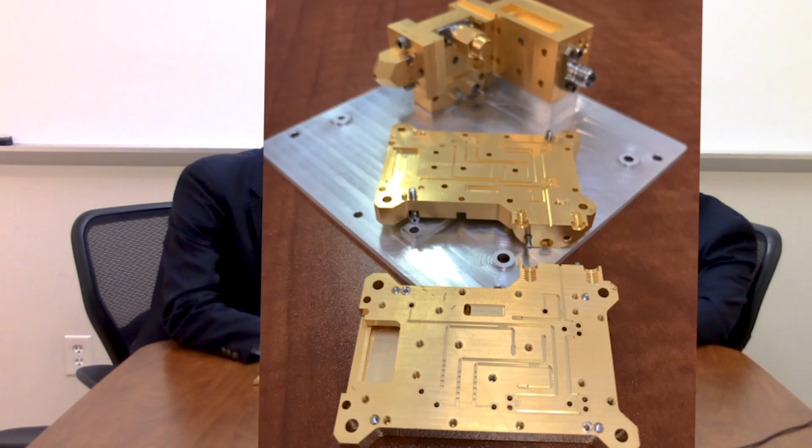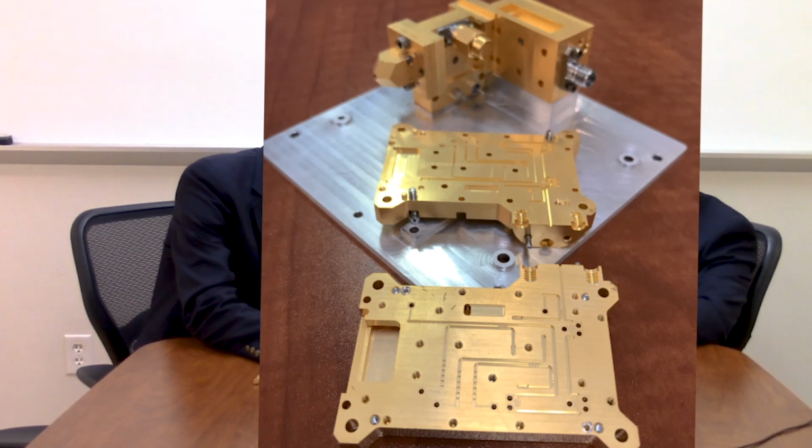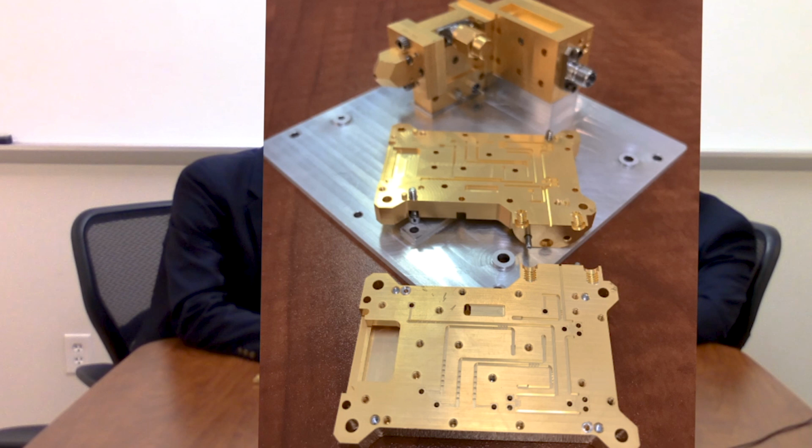And so you have some of the components here. Can you tell us, what type of circuitry and devices go into making up this product? Yeah, certainly. So this is a mock-up of the IceCube science plate. So it was a 3U CubeSat where each U is a 10 by 10 by 10 centimeter volume. And the actual front end, the receiver part, the millimeter wave part, needed to fit on this 9 by 9 centimeter plate and take up about 2.5 centimeters height.